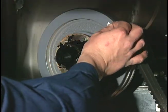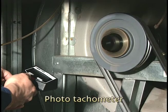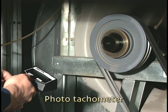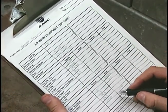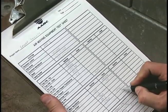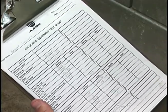A piece of reflective tape is used with a phototachometer. The tachometer counts the number of reflections in a set time period and records the RPM. To ensure accuracy, the technician takes successive readings until two consecutive repeatable values are obtained. The technician records this as actual RPM on the appropriate forms and compares it with the specified RPM.